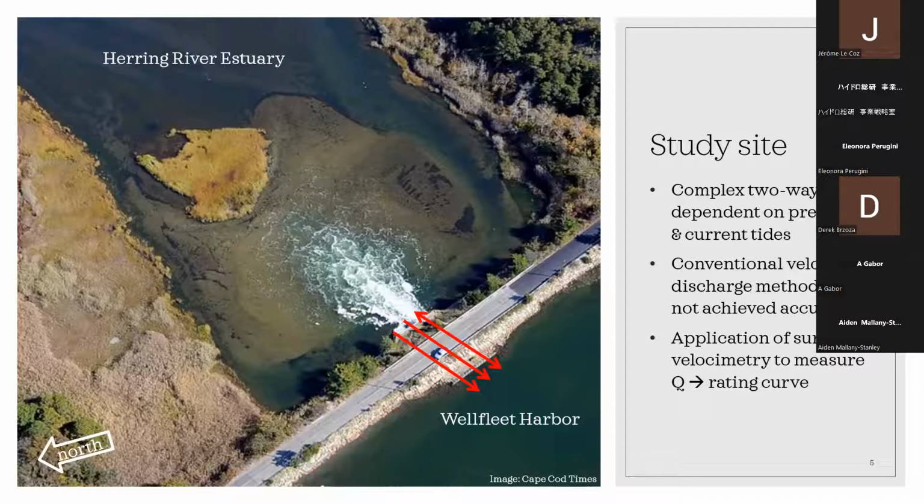So this is just looking top down. At the previous slide, I'm not sure if you noticed, there is water coming out of the dike. Here, the water's going into the dike. So you see this huge hydraulic head that builds up at high tides. And basically that is just forcing water at really high velocities through a very narrow constriction. So you'll notice there's 3 arrows on this slide. Those represent the 3 tidal gates that make up the dike. And you'll notice only one of them allows water in while all 3 allow them out.